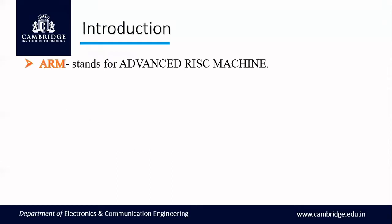ARM stands for Advanced RISC Machine. As the name itself says, all the ARM processors follow the RISC architecture. RISC stands for Reduced Instruction Set Computer. All RISC machines' instruction set is said to be simple, which means the machine code for almost all the instructions are of the same size, which allows deeper pipelining to be possible, and that in turn increases the speed of the processor. So all the ARM processors designed by the Advanced RISC Machines Limited follow the RISC architecture.